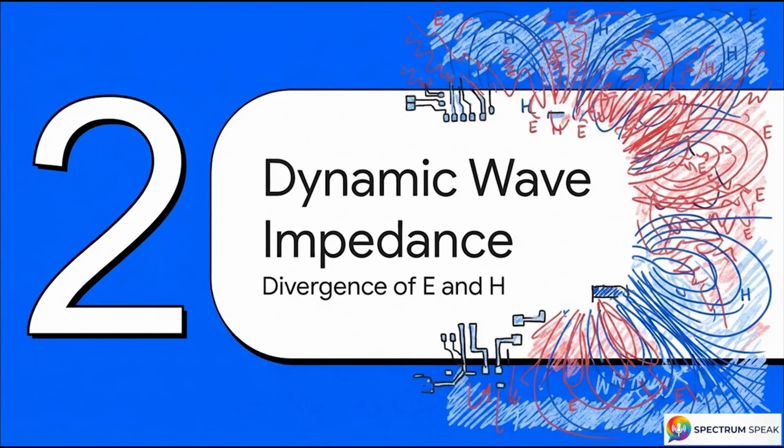Moving on to Section 2, Dynamic Wave Impedance, the divergence of E and H. So as we push past that lambda over 6 boundary and go deep into the near field, something wild happens. The electric and magnetic forces just completely decouple. They stop moving in lockstep, and they often fall totally out of phase. Depending on the physical geometry of your traces and components, one of those fields is going to completely dominate the other, creating a highly chaotic, highly reactive environment.